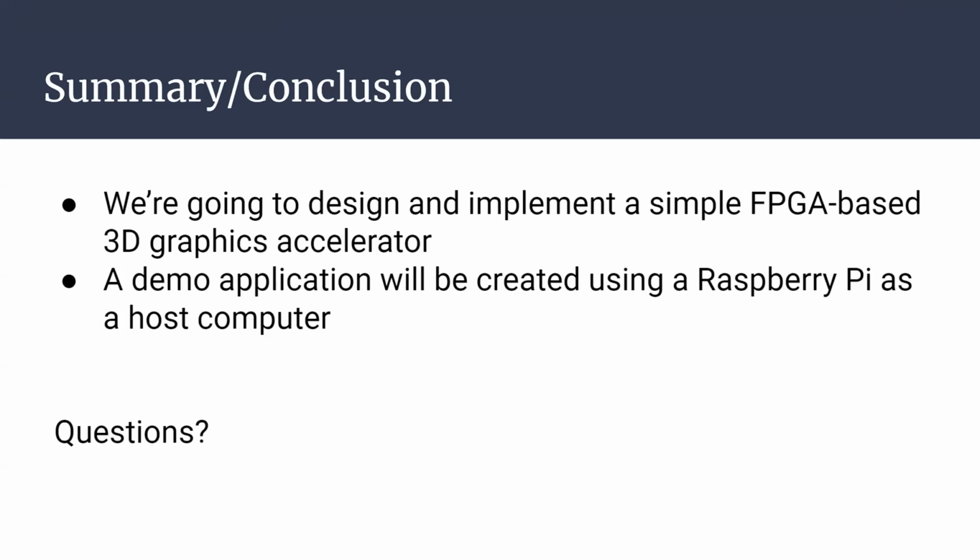Well, what we're seeing with this project is that you don't actually need that much power in the FPGA itself. With how FPGAs have been evolving and progressing, this is a good thing that you could add on top of existing projects. Why not add an interface that you could actually see? The only issue is that it's very memory dependent. That's why we're stuck at 800 by 600 with 8-bit color. We could up that to 12-bit color, but then we'd have to reduce our resolution, or we could increase the resolution and reduce our color depth. That's really just the limiting factor.